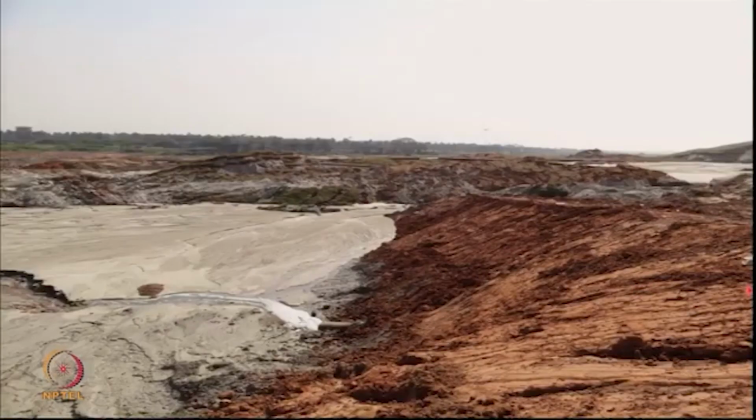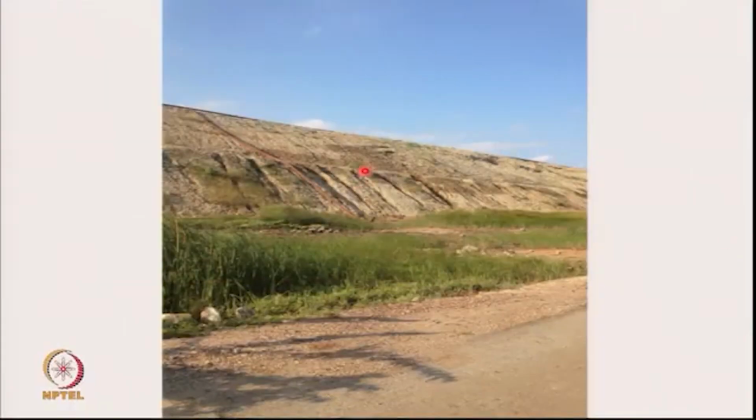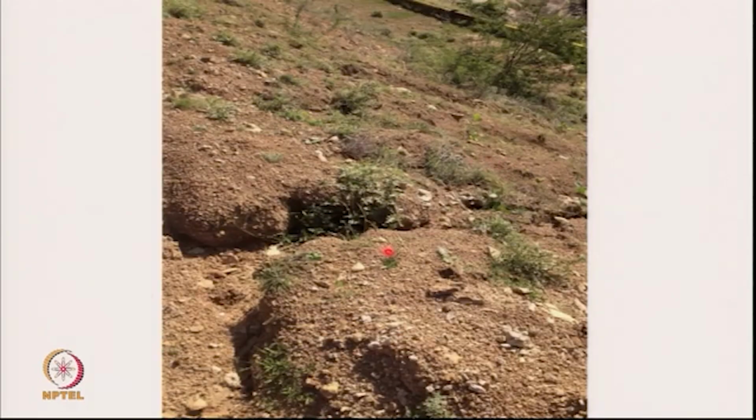Just to recall, this is an ash pond where the ash has breached and has come out. This is another tailings impoundment in which there has been a failure of the slope. Here there has not been any failure, but you can see vertical erosion and seepage paths. Can you see the wet downstream face? Quite clearly the phreatic line is not being captured. If the phreatic line was captured, you would have a dry slope. And this also shows large movements on the downstream face of an upstream raised embankment.